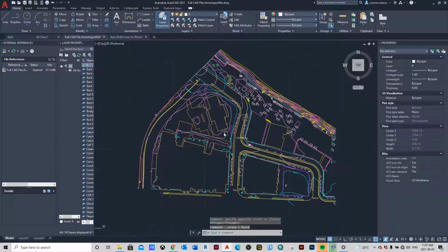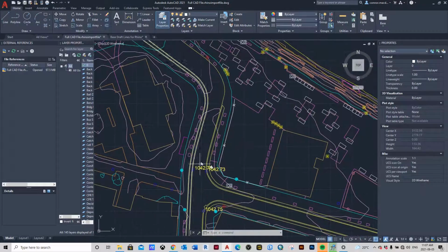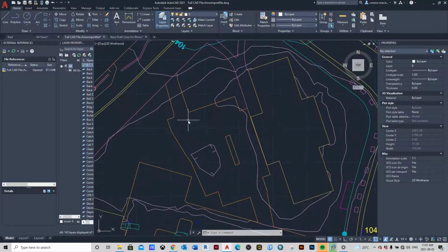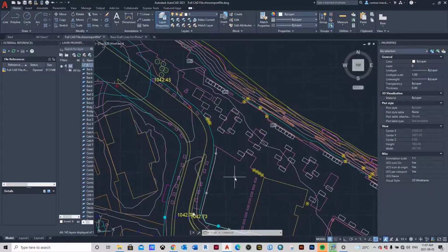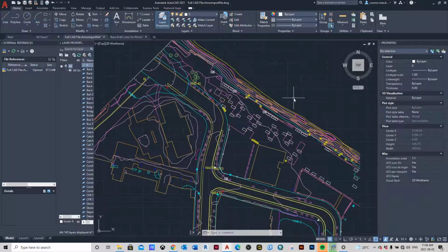Okay, so I've jumped ahead a little bit here, and right off the bat, this looks way cleaner. There's way less information here that Rhino has to process. It's a lot simpler and more pared down. But when you look in here, you still see topo elevation points, lots of pieces of terrain, little bits of information that we don't really need right now. So from here, I'm going to show you a tool that's really good for wiping out any layers that we don't need. I'm going to show you right now the layer delete tool.